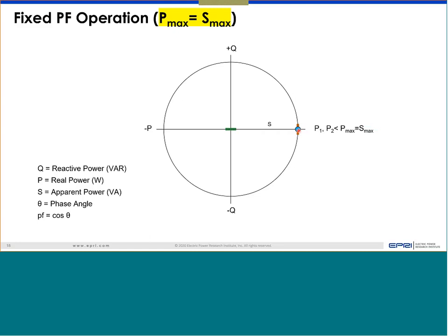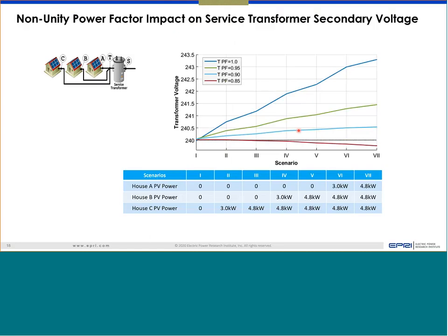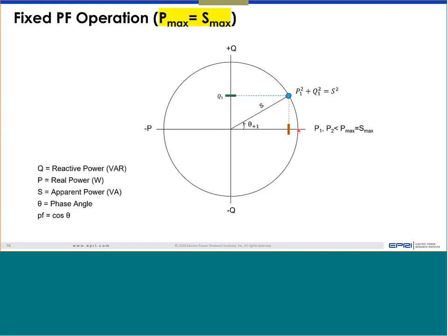In that condition, when the inverter is generating its maximum power, suppose you ask the inverter to operate in a non-unity power factor mode. Previously it was operating at unity power factor, no problem, because there was no reactive power demand. The entire VA was used to generate the kilowatts.